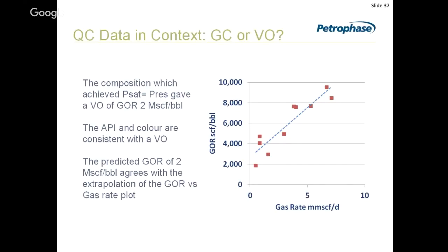By actually turning the data around like this and plotting it, we can work out what the initial fluid was. We can use our equation of state model to predict the initial fluid properties. And indeed, this did prove to be a volatile oil rather than a gas condensate. But the clues were there. It's just picking up on them. For one thing, the condensate was black. And condensates, well, they can be dark, but really oily black should give clues.